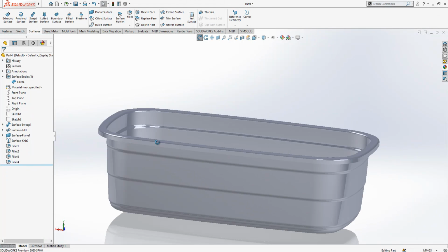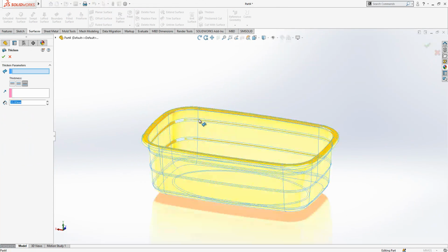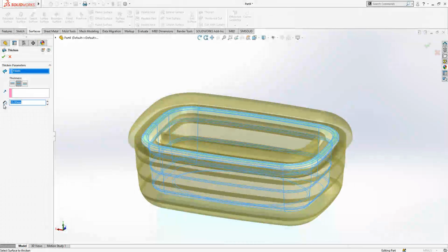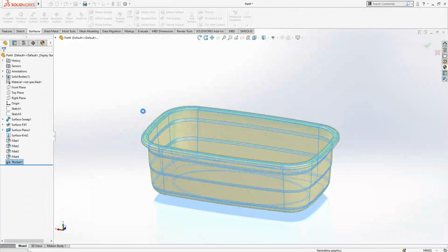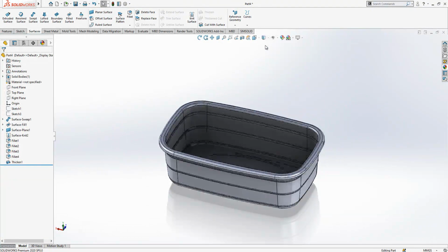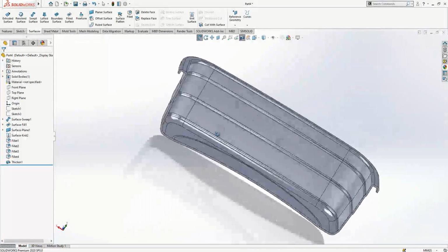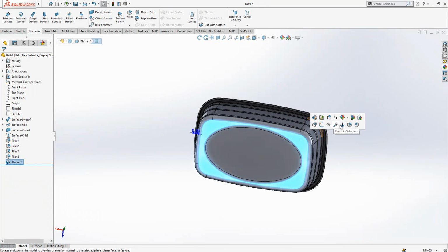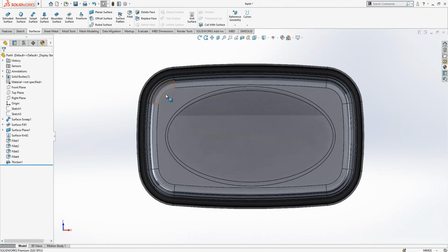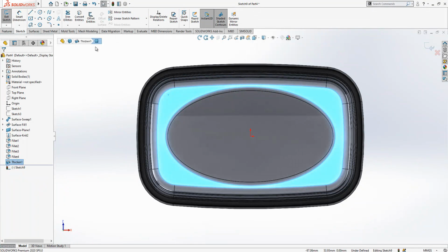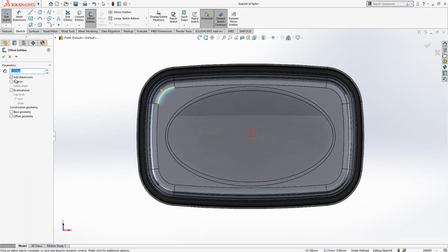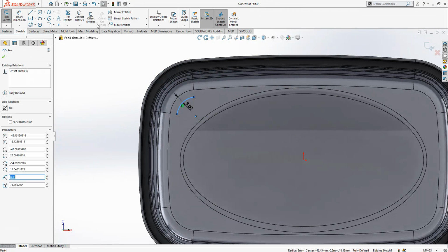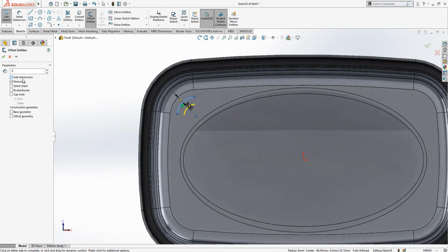Pretty much fine. And now we can make it thicken. In the middle, 0.5. So your thicken will be 1 millimeter. Section, you see something like this. It is looking nice. And then I will create here my little feet. This is selected. And I will make an offset of 3 here and 2 from here. 1.5 is better.